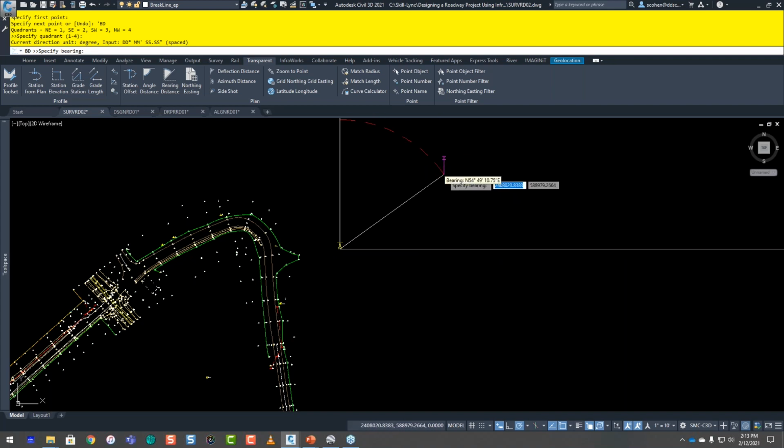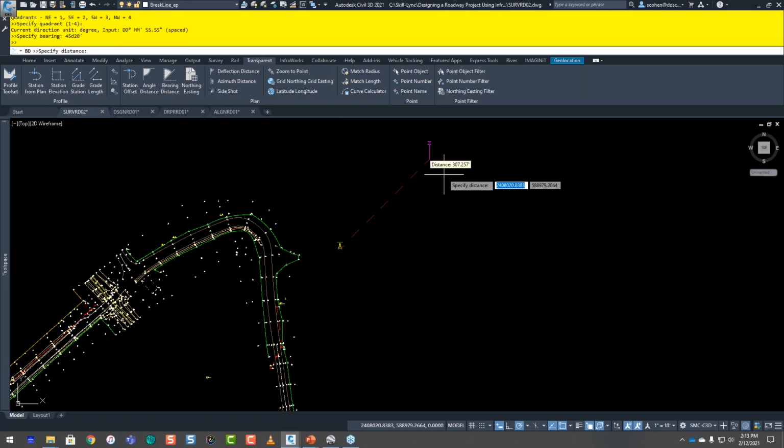Now, in this case, like I said, it's not with all commands, the dynamic input does not kick in, but it is at least showing you kind of the format that you have to use. So if I want something at 45 degrees, 20 minutes, there's a couple ways to do it. You can do 45D, that's one way to do it, and then 20 minutes with the apostrophe, and then press enter. Okay, that works just fine. You can also just do dashes if you want to as well, okay?